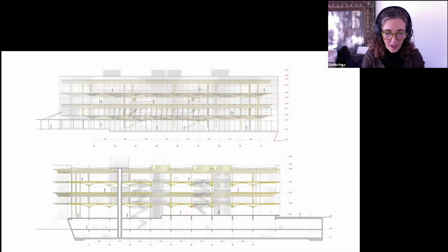The beams, with a span of 18 meters, are supported by solid columns with a cross-section of 300 by 700 millimeters made of laminated wood. The direction of the beam changes by 90 degrees from one floor to another. This allows all the beams to be supported every 18 meters, and the beam has a vertical traction cable up to the floor, to the upper floor beam.